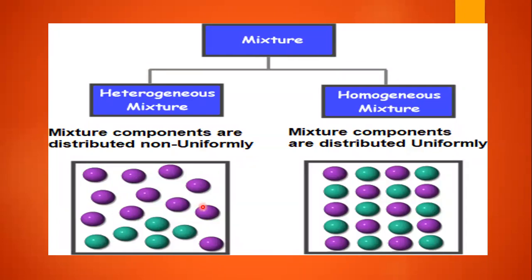Otherwise the density is less. If the density is less, whatever fuel is there will travel throughout the air and contact the combustion chamber and piston head. If the fuel is going to touch the cylinder walls and the piston head, then it is not helpful for combustion. They may touch these walls and piston head, and there will be wastage of fuel.